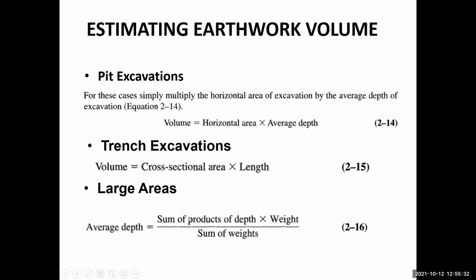So for example, in the case of the pit excavation, simply multiply the horizontal area of the excavation by the average depth of the excavation. So here we can simply find the volume of the excavation by horizontal area times the average depth.